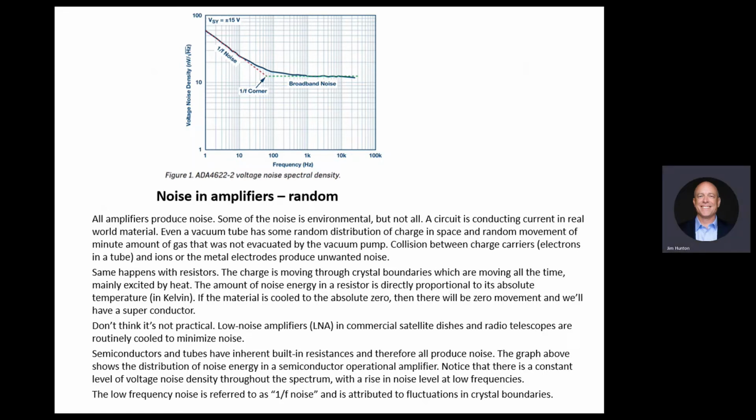The noise on the output that you care about is referred to the noise at the input. Yeah, that is true. You still need to look at it. You're right. In most cases, what we do is actually multi-stage. If the first stage has a lot of amplification, it's the only stage that matters, and the rest of the stages are lower. If you have a first stage with lower amplification, then you need to look at the second stage as well.